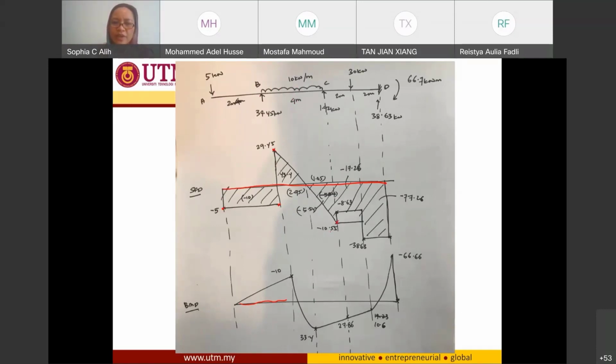Okay, negative 10.55, and I have going upwards 1.94, so I have plus this one, so this is where I got this one. So this is wrong. Okay, this line is wrong, and there is no load between this point and this point, so I go straight. And another 30 kilonewton going downwards, so -8.63 minus 30, so I have -38.63, and there is no other load